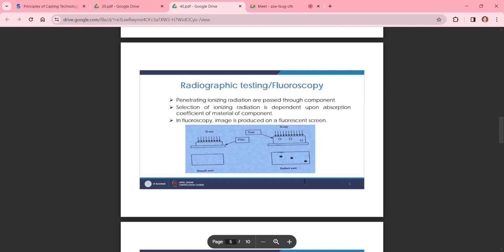What will happen if the defects are inside the surfaces? We cannot go with magnetic particle testing or dye penetrant testing, because those will not penetrate inside the surface, as there is no hole or porosity for the magnetic particles or liquid dye to get inside the castings. For checking inside defects in castings, we generally go with different techniques like radiographic testing, eddy current testing, or ultrasonic testing.